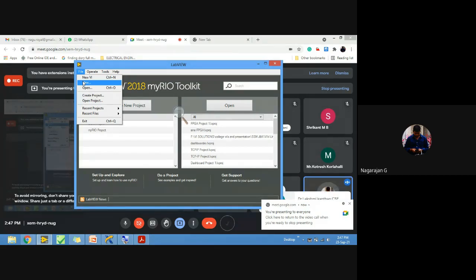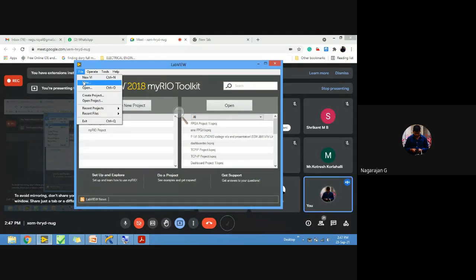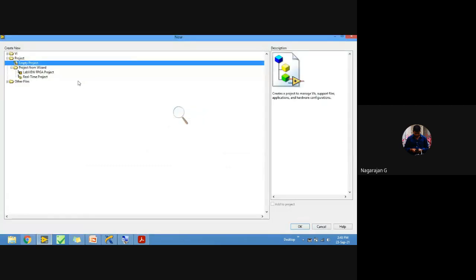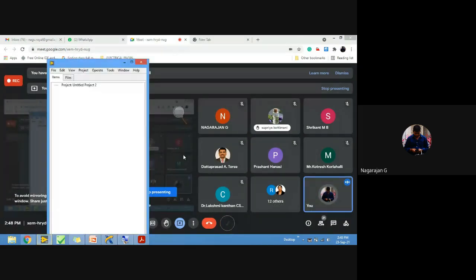Fine. So now we are going to learn how to have a data transfer between different targets here. One is going to be the LabVIEW target and another one is going to be the RT target. And as we discussed about this FPGA, the most advantage of having this FPGA program is that we can go for parallelism. So how can we achieve this parallelism? Parallel operation. By having this option of parallelism, FPGA is considered a very powerful tool and technology.